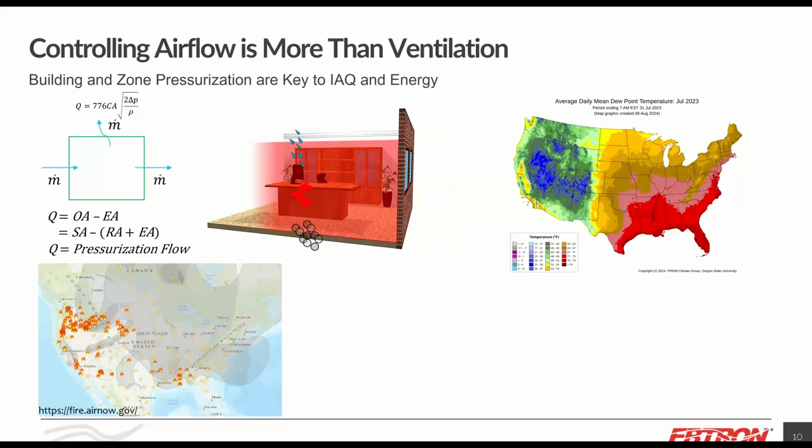You want to keep pressure on the building. You want to try to maintain ventilation to dilute what's inside the building. And you want to make sure that your exhaust is not greater than your supply, or your ventilation into the building. Otherwise, you're going to be negatively pressurized and you're bringing in smoke through the front door, and through cracks and crevices in the building.